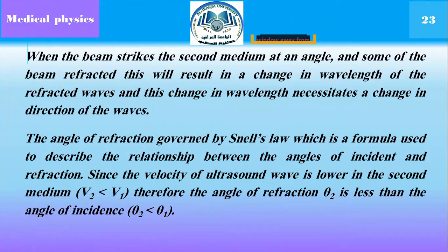The angle of refraction is governed by Snell's law, which is a formula used to describe the relation between the angle of incidence and refraction. Since the velocity of the ultrasound wave is lower in the second medium, meaning V1, the velocity 1, is bigger than velocity 2, therefore the angle of refraction theta 2 is less than the angle of incidence, meaning theta 1 is bigger than theta 2.